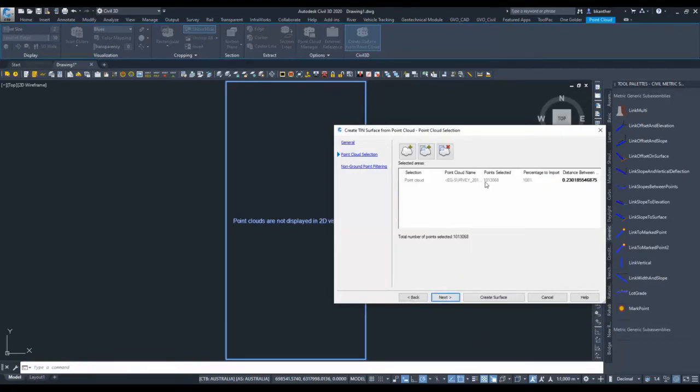Now it's going to tell you here, it's going to bring 1 million points into this session. It is possible we could filter down further. I could make that distance between points a meter. I'm happy with less than 2 million points generally. Although if you are working with gradings, I would highly recommend ensuring this is even below 500,000 points because it can cause lots of performance issues.